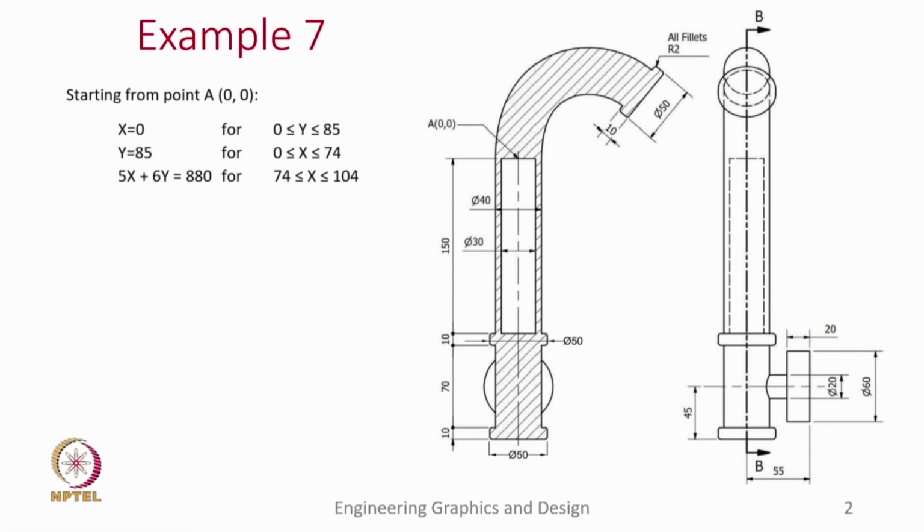to model it. As we can see, we have a vertical column and at the top of the vertical column there is a curvature. So, the column is bent and this curvature is defined using a spline. The equations of the spline are shown here. So, let us see, these are defined about a point A. This point A is shown to be here. Okay. So, what we see is that these equations do not represent the spline, but the control vertices of the spline.